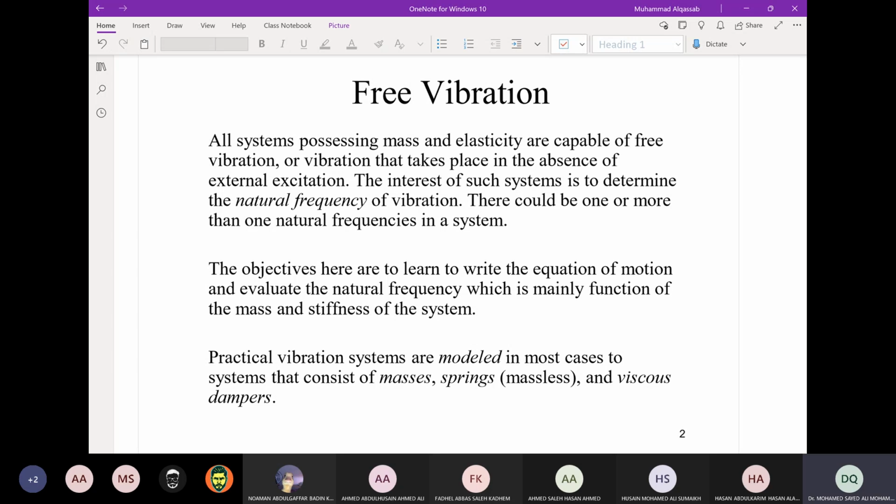So one way of determining the natural frequency is by letting the system oscillate under free vibration. You can determine the frequency by using some instruments, an accelerometer maybe, and other devices that record and process the measured vibration to find the natural frequency. Or we can do this mathematically. We will do it here in this chapter.